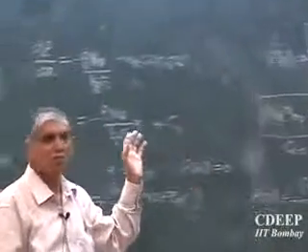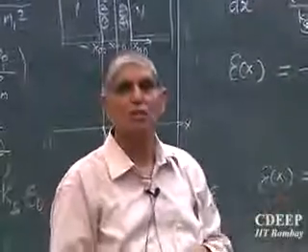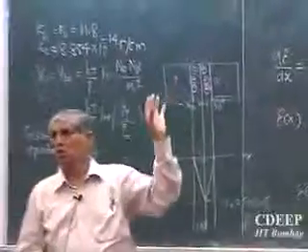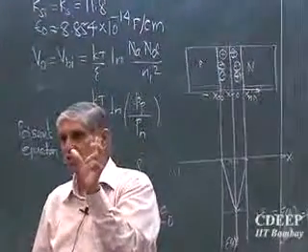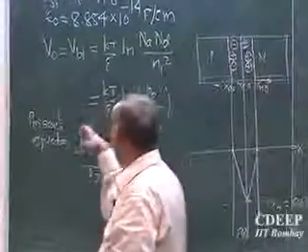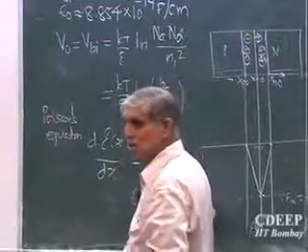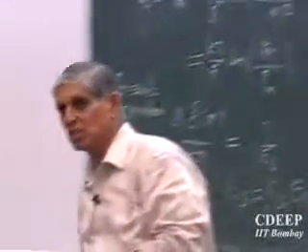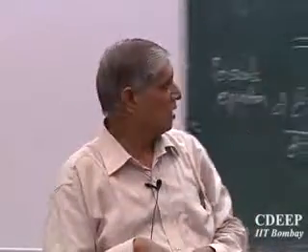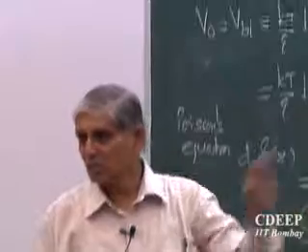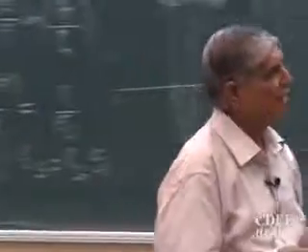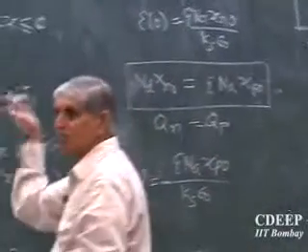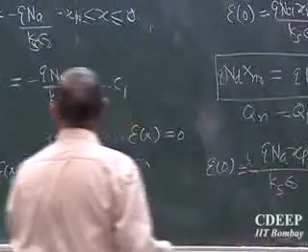Is that clear? So what is this method of calculation? This is space charge analysis. The diffusion layer is also called the space charge. Poisson's equation actually says dE by dx is space charge divided by permittivity. So actually this is the space charge which we graph. Is all clear? So let's come back. So what will happen in the linearly graded junction? Maybe we will solve that, if time permits.